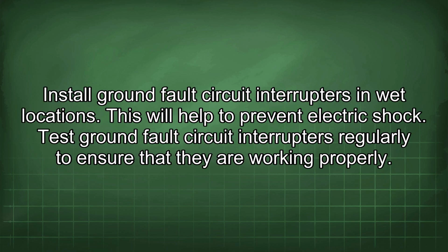Install ground fault circuit interrupters in wet locations. This will help to prevent electric shock. Test ground fault circuit interrupters regularly to ensure that they are working properly.